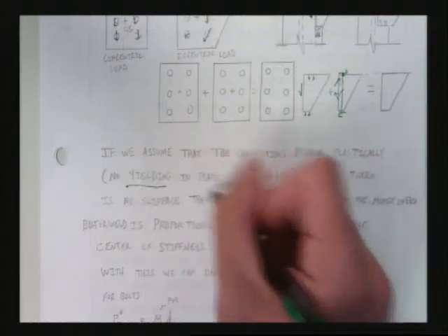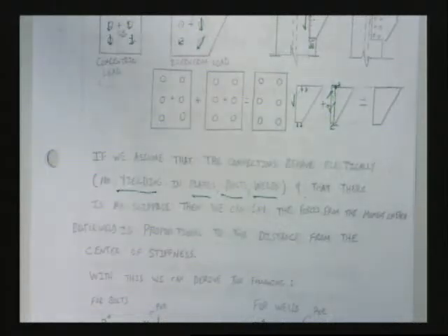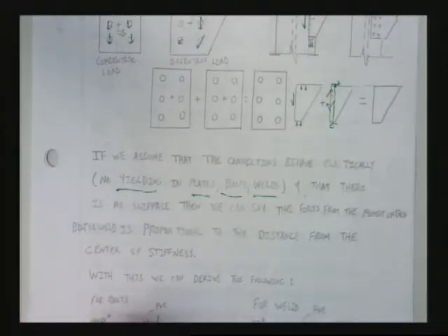And we're assuming there's no yielding in the plates, the bolts, or the welds. Is this a good assumption? Do we have yielding in our bolts and welds? Yes. Do we have yielding in our plates? Yes. Is it conservative to assume that things stop right when they start to yield? Usually it's very conservative to assume that. Extremely conservative. And you've heard me talk about why engineers are scared of paper clips. That's why. Because paper clips are yielded to death, right? And we still use them all the time, right? Not that big of a deal.